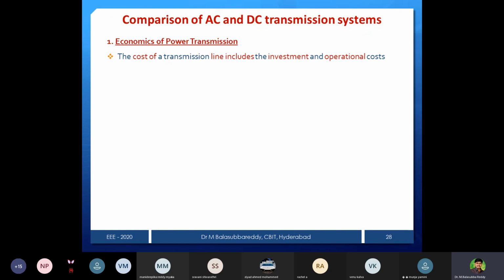How do you increase the power transmitting capability? That is what FACTS devices are used for. They reduce the impedance offered by the line using series compensators, and allow the maximum extent of power through the transmission line. Instead of erecting a new line, they use the controller to transmit more power. Using all these scenarios, you can get minimum cost, minimum loss, and better voltage fluctuation and stability. So many parameters lead to optimal power flow control and will decide that.